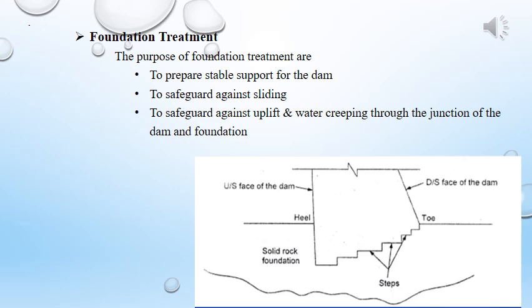Foundation treatment. The purposes of the foundation treatment are to prepare a stable support for the dam, to safeguard against sliding, and to safeguard against uplift and water creeping through the junction of the dam and foundation.